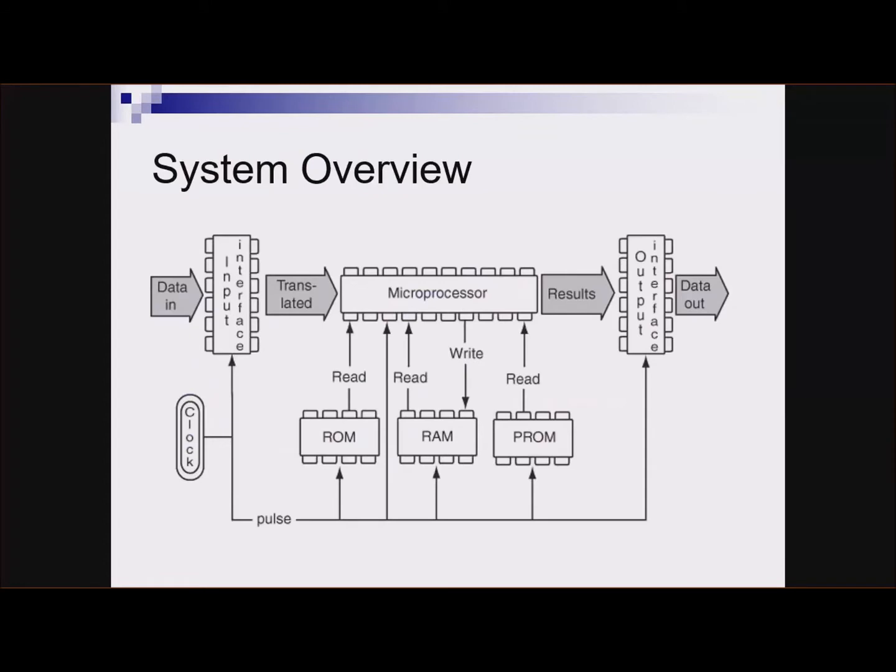So here's kind of a diagram of the entire process. And notice that it flows from left to right. So over here is data coming in from various sensors. The input interface, all right, so this is what I was talking about, when you've got maybe analog to digital conversion, maybe frequency to voltage conversion. So a sensor puts out a varying frequency. That has to be converted somehow. Basically, everything has to be converted into a number that the computer can work with.